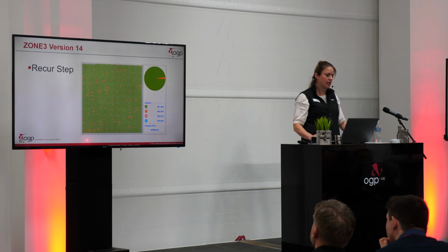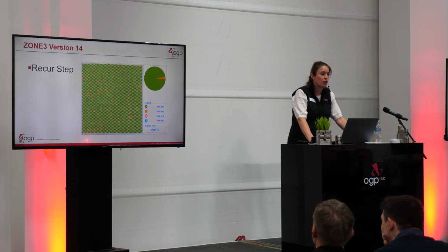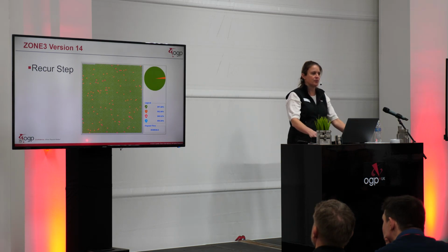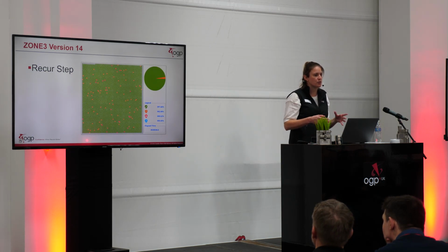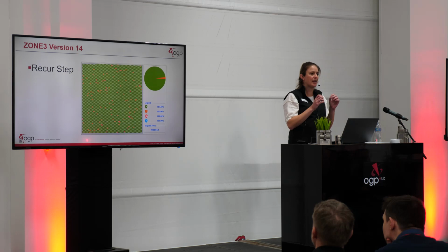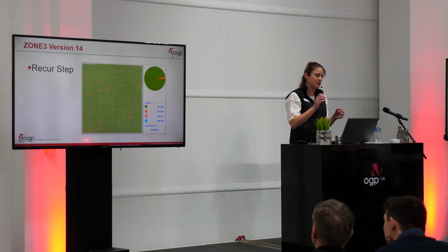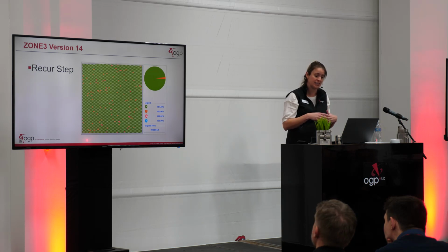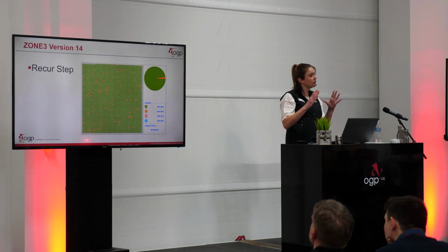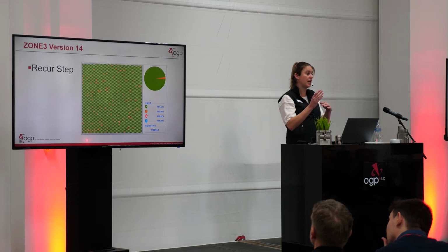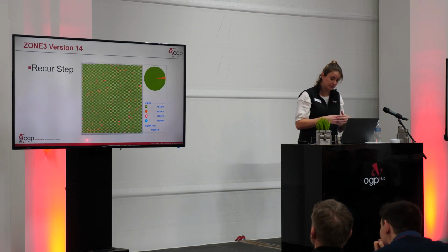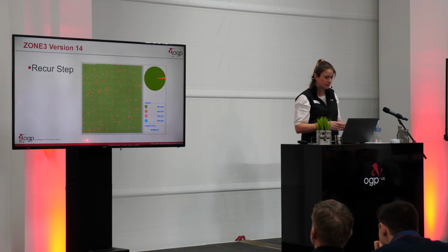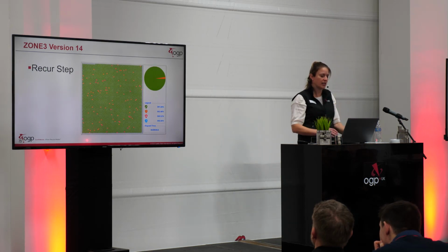And the first major enhancement is what we call a recur step. This was designed for circuit boards or stamped parts where we have many of the same exact feature and you want to measure them all. Before you'd have to program them each individually or copy it; the recur step made programming them very easy. When it's running a recur step, you actually get a status report of how many passed, failed. You get statistics automatically, and it's a very good visual indication.